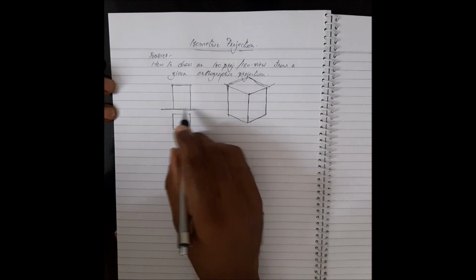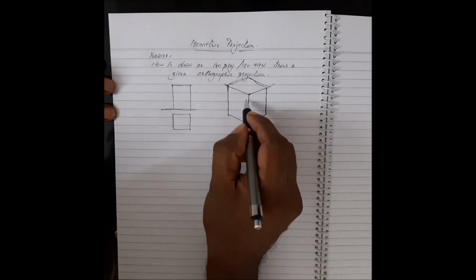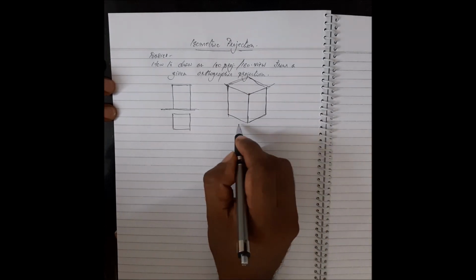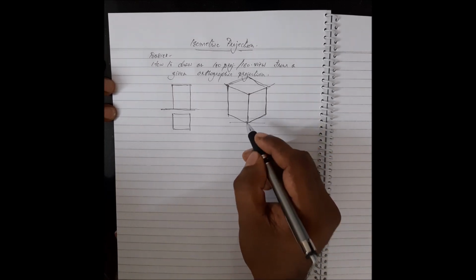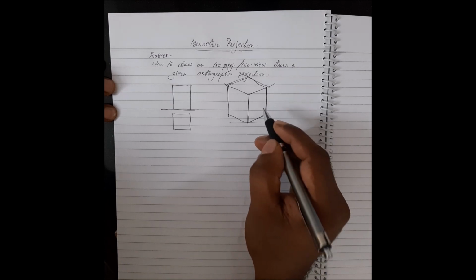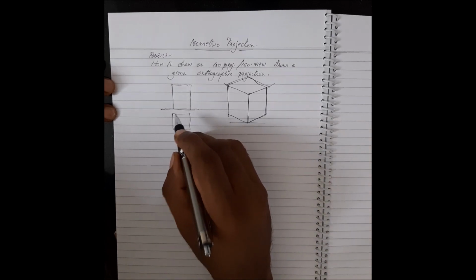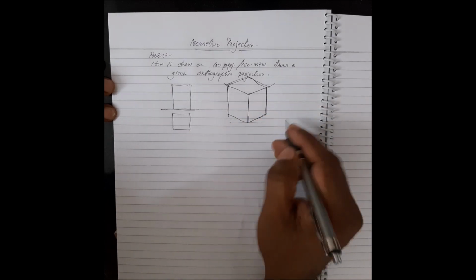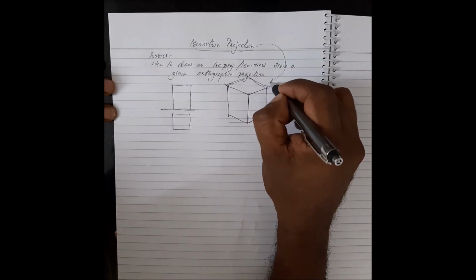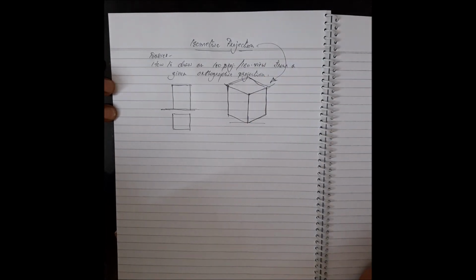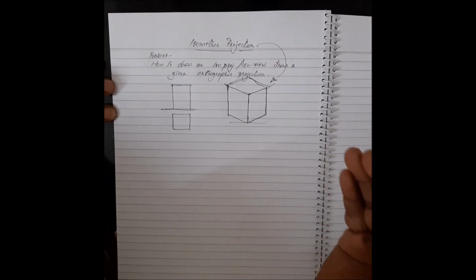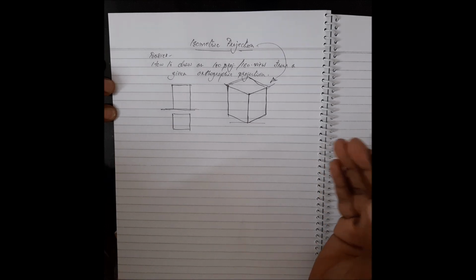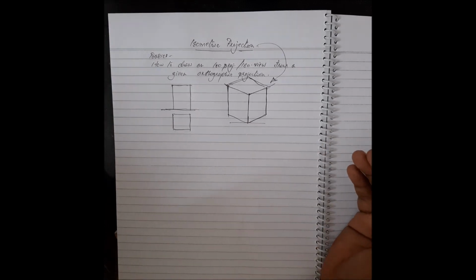Now what is the difference between these two? The moment you see this picture, at a glance you'll get an idea, okay, this is a square prism, because it actually gives you a three-dimensional feel, whereas this doesn't give a three-dimensional feel. That is the basic difference. Isometric projection always gives you a three-dimensional feel. Now how do you get a three-dimensional feel? You bring the solid to something called isometric position, and then what is the specialty of that position?